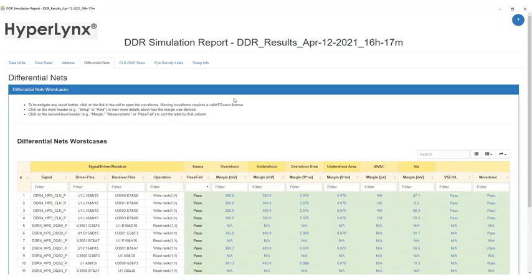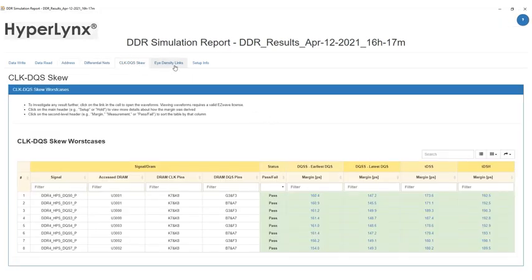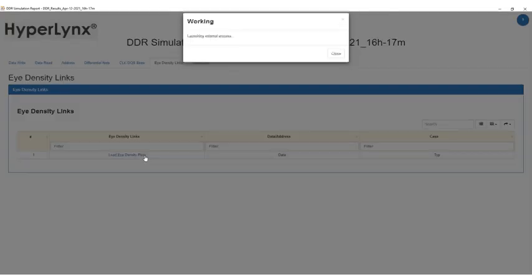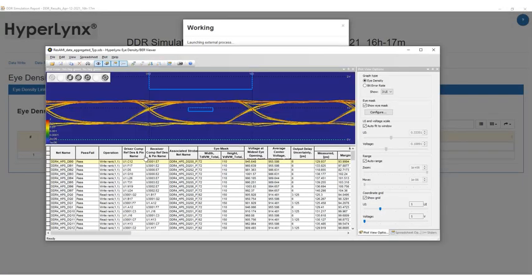This is very important for me as a PCB designer, because this reflects if the PCB layout is robust and passed through the final sign-off when other effects like crosstalk and power aware are considered as well. We can see that we are in a very good shape in regards to the DDR4 interface. In the next step, we want to make sure that all other nets are electrically correct as well. This is done with HyperLynx DRC.